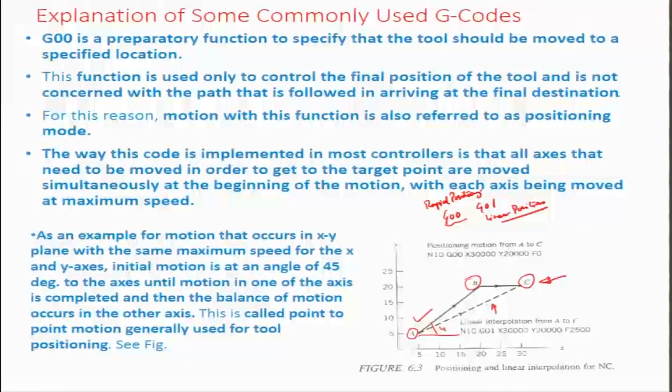And so, therefore, the best idea for minimum time arrival of a tool from point A to point C is to operate, to an extent possible, where x could be equal to y, where the full speed of both the motors could be initiated, and then once it reaches that point, namely B, where the angle here is about 45 degrees corresponding to the x equal to y line, you can actually switch off one motor and let only the excess motion be covered in the x direction, again at full speed. So, time wise, in an NC XY table, it makes perfect sense to say that the path ABC is more quickly traversed in comparison to AC. You can see the limitation in AC is that one of the motors, particularly in the x direction, has to be slower so that it reaches between A and C.